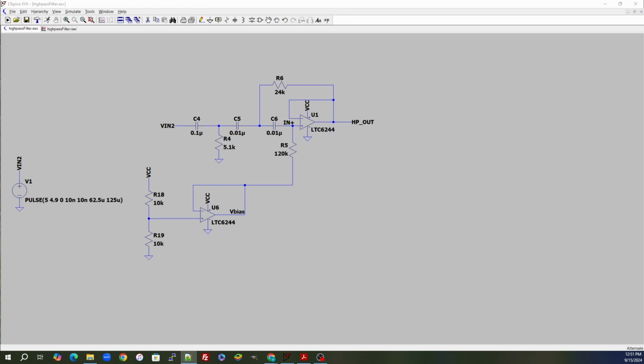What we want to do is shift that entire signal down so that instead of reading the 100 millivolts going around 1.65 volts, we can actually see 200 millivolts going from 0 volts to 200 millivolts on the output of the circuit. Then we can feed that into our processor, and the processor can just read the high on that, and we will see the peak-to-peak voltage just by taking a reading and averaging out the high output, the maximum of that signal coming into our microprocessor.